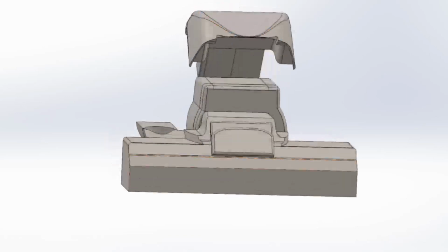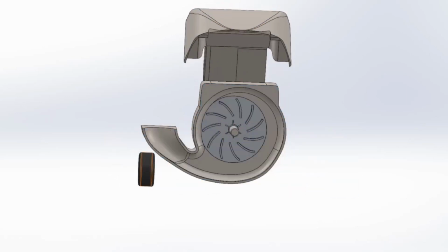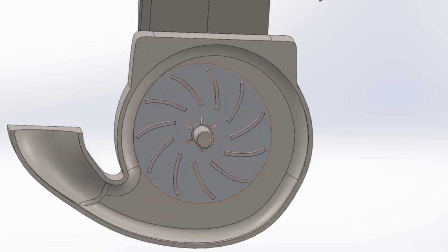You can open the top, and when it gets inside the impeller, we can see the impeller blades. These impeller blades will catch the fluid that enters in the middle of the pump. You can see that the blades are kind of bent in a non-intuitive manner. You would expect them to bend in the opposite direction, but because the fluid increases its velocity as it moves radially outwards, the blade is actually, relative to the fluid, in a correct position, and they will catch the fluid